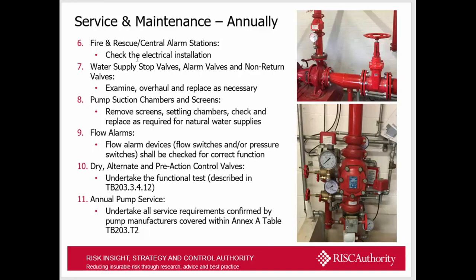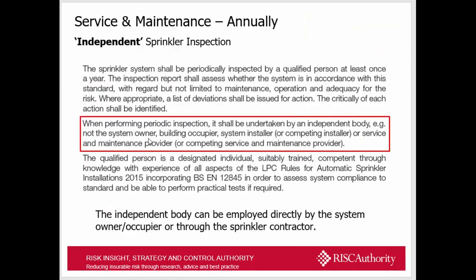Dry, alternate and pre-action control valves: a new requirement came in, I think it was last year, so undertake a functional test as described in TB203. So that must be performed on an annual basis, and undertake all service requirements confirmed by the pump manufacturers on an annual basis, also covered in Annex A in Table 2 of TB203.